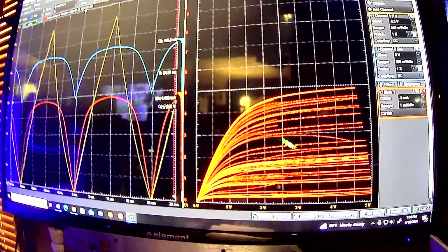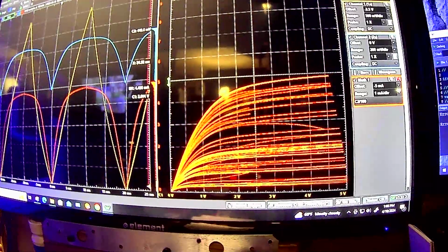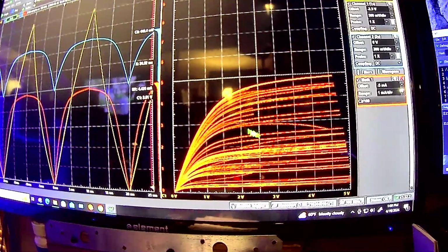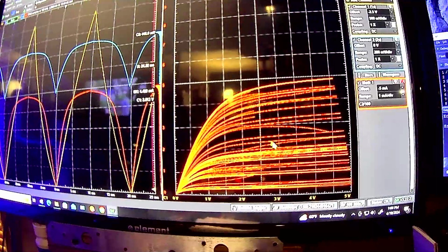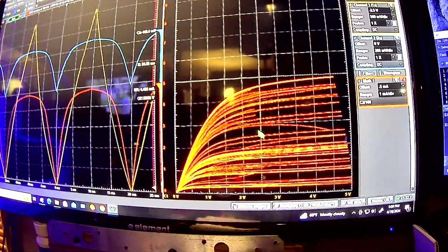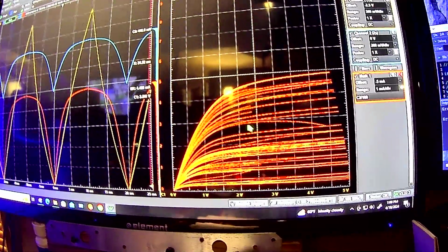So that's where your load line would be. It'd go from like 5 volts to right around 5 milliamps. So again, you'd actually operate it right around here with this device, because that would be on a load line curve, so around 2 to 3 milliamps. That's fairly linear.